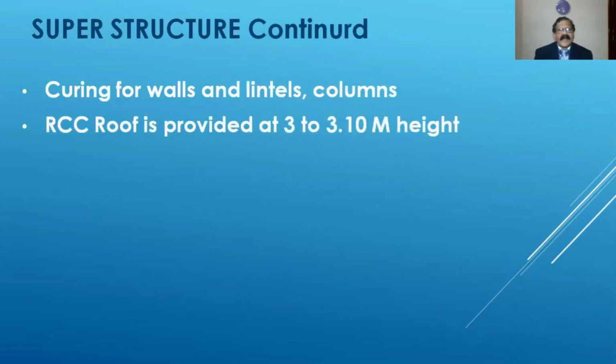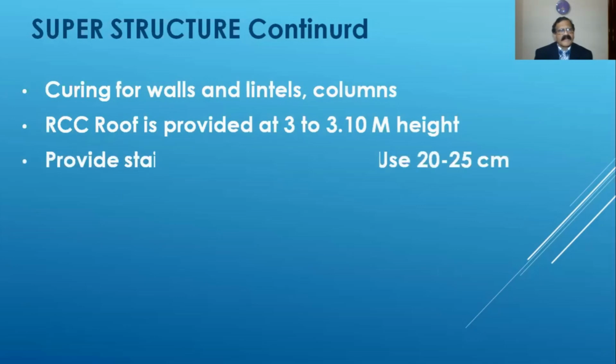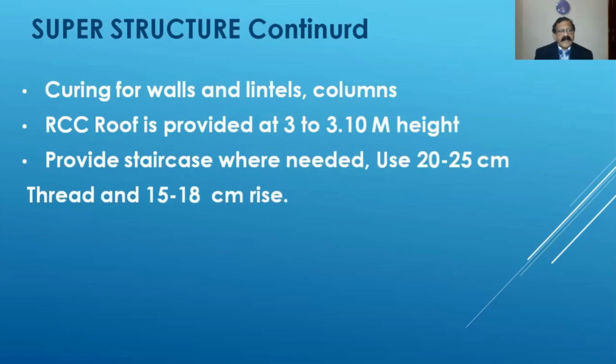RCC roof is provided at 3 to 3.1 meter height. Provide staircase wherever needed. Use 20 to 25 centimeter tread. Tread is nothing but the horizontal distance of a step, and 15 to 18 centimeter rise, which is the vertical distance of a step.